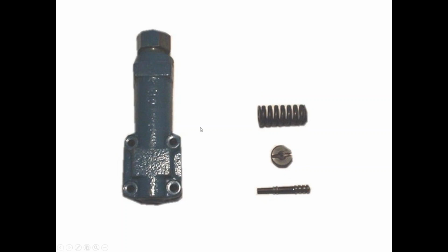Okay. Now look at that valve spool. You see right here a small orifice. This orifice is about the size of a small paper clip. You could stretch it out and run the paper clip through the hole to clean it out. But if this hole gets plugged up, and it takes very little trash to do that. If that hole gets plugged up, that's exactly what's going to happen.